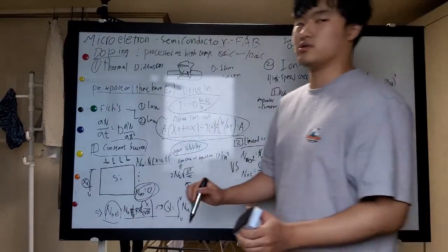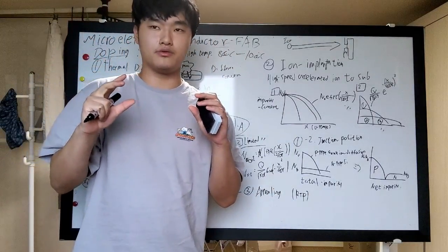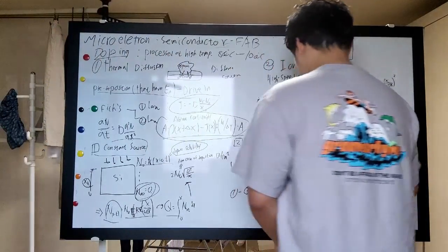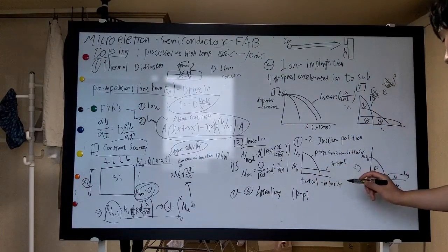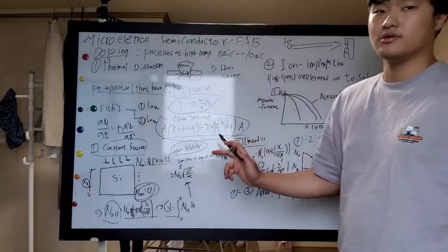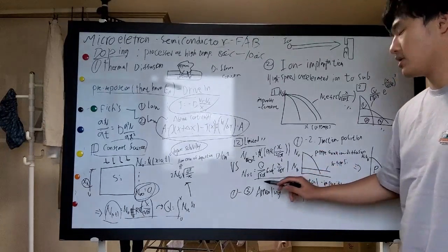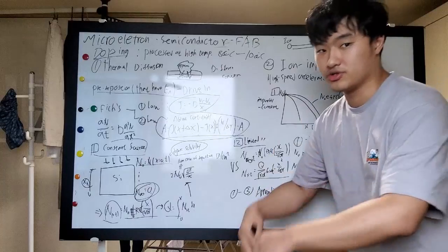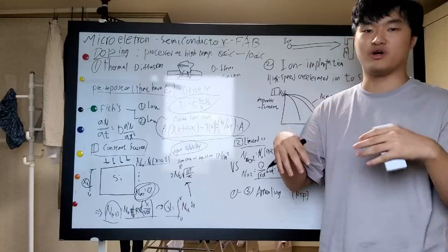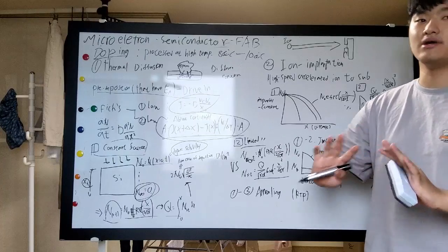So it means just one time with a limited amount, the dopant amount will be set. So here are the equations, and for the limited source, the equation will be related to the error function. So finally it will be related to how the diffusion will go deeper, and if there is more energy, and if the diffusion coefficient is higher, the deeper and larger the dopant area will be.